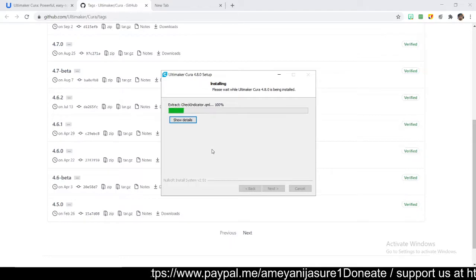So those STL files you can easily open in Cura, and there is a standard procedure of slicing that software, selecting the printer, then applying different temperature zones and layer height, densities, everything we will be discussing in the coming videos. Those all things can be done in Cura, and the output of Cura is basically your G code, where that code will give the location of your tool which is moving in your Ultimaker printer. Okay, so that is basically a G code file.